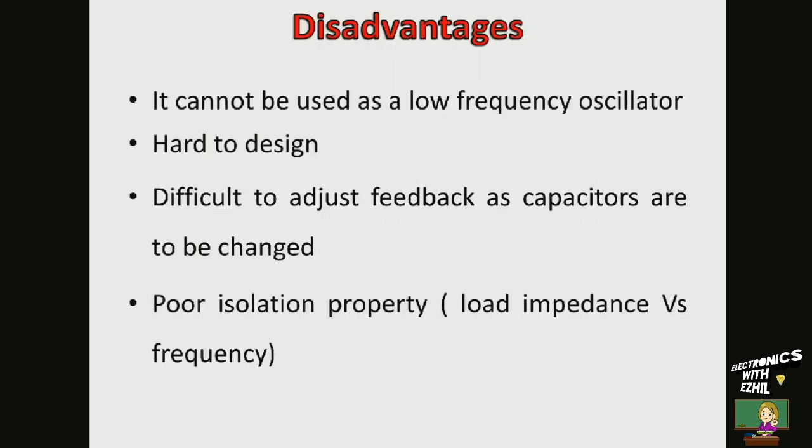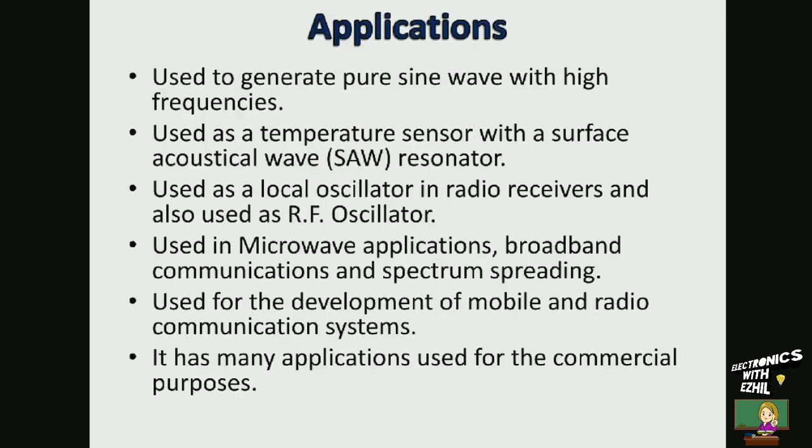Disadvantages. It cannot be used as a low frequency oscillator because high value inductors are not practically possible. It is hard to design, and it is difficult to adjust feedback as capacitors are to be changed. It has poor isolation property.